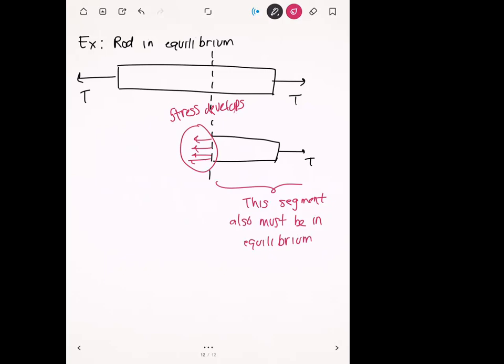And so since that surface has some non-zero area, it doesn't make sense for that stabilizing force to be concentrated at a particular point. And so this stabilizing force is then distributed across the entire surface. Since we have a force that's distributed over a surface, that's why we call it a stress.